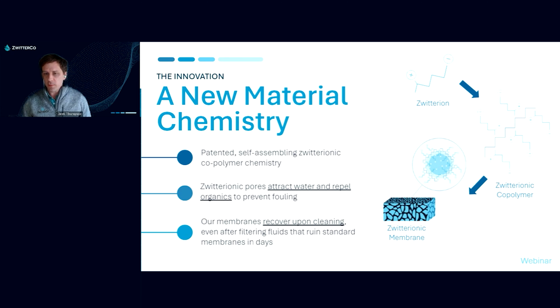So because irreversible organic fouling is still a great challenge, membrane manufacturers and researchers have been looking for ways to produce a step change, a revolutionary new way to handle organic fouling. One of these new chemistries relies on zwitterions. Zwitterions are small organic compounds that have an equal number of positive and negative charges. They are extremely hydrophilic, or organic repelling. And people have been trying to incorporate these into membranes for decades.